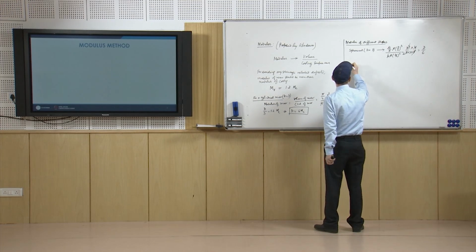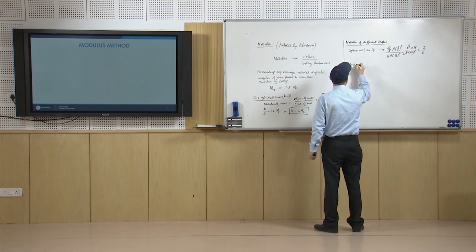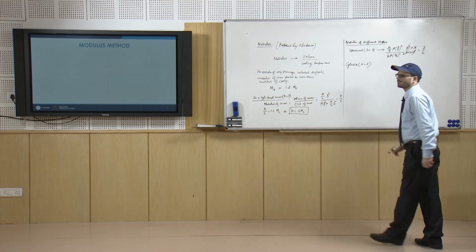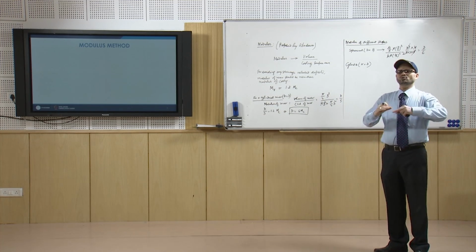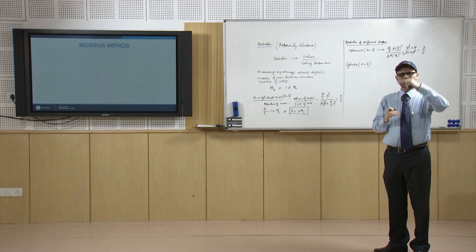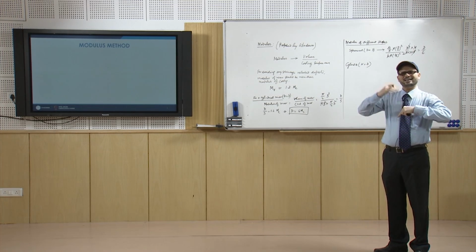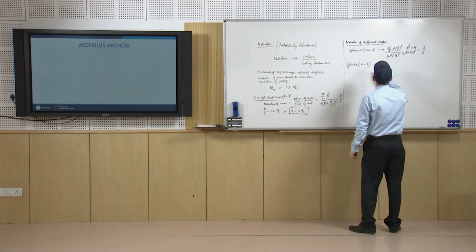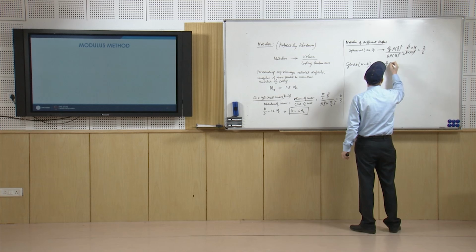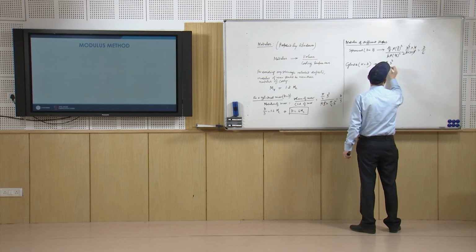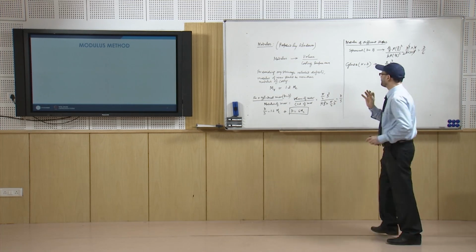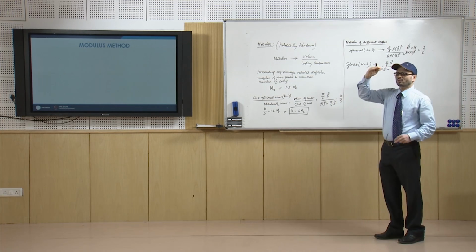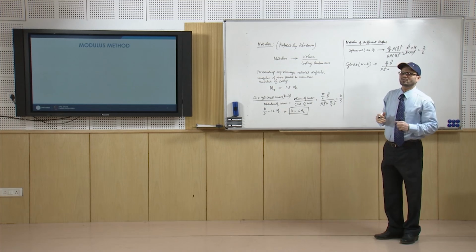Similarly, for a cylinder with h equal to d, and you assume that both the surfaces are acting as the surface which expose the heat. In that case, the volume will be pi by 4 d cube and surface area will be pi d square, the curved surface area, plus pi by 4 d square on the top and pi by 4 d square on the bottom.